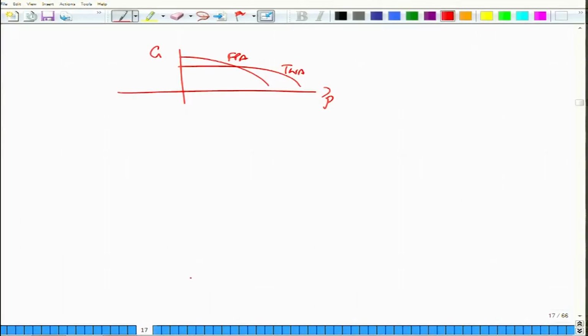The big advantage of course is that a travelling wave amplifier will never laze, because there is very little feedback that the amplifier is sustaining. On the other hand, Fabry-Perot amplifiers can be made to laze, even externally, by actually putting the entire SOA in the middle of a bigger cavity, and then increasing the feedback of that external cavity. So SOAs are also used for lasers. Not a very good way, but it is also used for lasers, and most importantly SOAs offer high nonlinearity, much higher than the nonlinearity of fiber, and therefore they are actually excellent for many nonlinear optical signal processing applications.